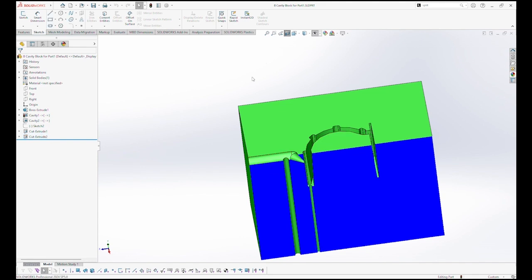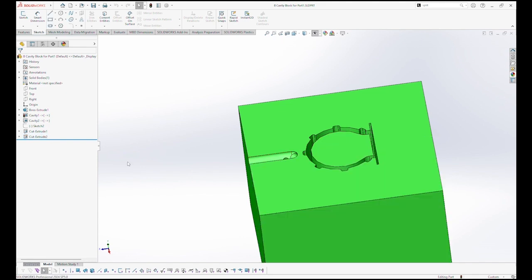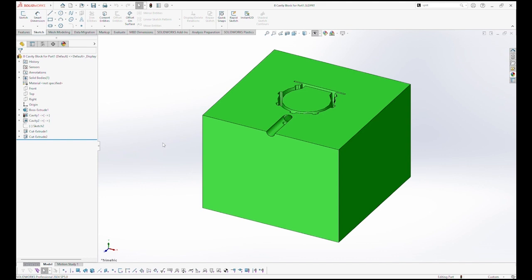And so a subgate is always the preferred method to produce a part if possible, simply because there is no post-mold interaction required of the part. After the part is ejected from the cavity and the runner is ejected, end of arm tooling will come in and grab the runner and dispose of that. It'll be reground and reused or disposed of, depending on what the material is and what the specifications are for the customer.